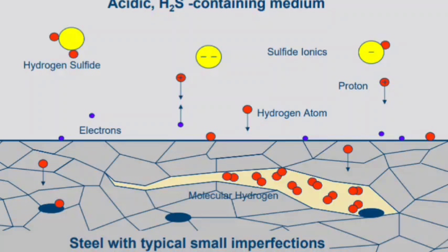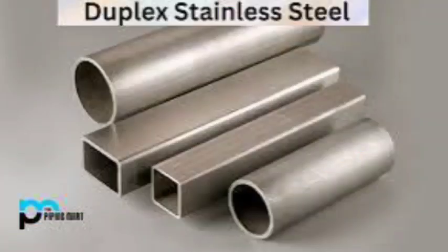Currently we are doing one applicability package. In that, our equipment are duplex stainless, like the de-oiling unit, IGF vessel, things like that. For duplex in produced water treatment, what is the maximum operating temperature? Is it 80 or 100? I think it is 80. Till 80 degrees C they will specify DSS, and till 100 degrees C they go for SDSS in the produced water treatment circuit.